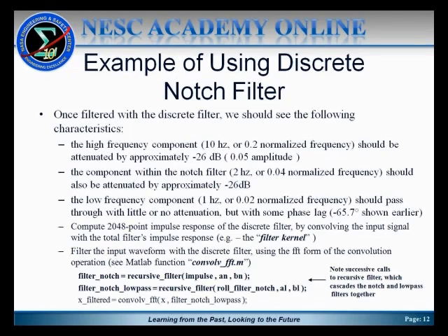And the two functions we're going to use, one we've talked about before, is recursive filter. That's just an implementation of a recursive filter where you pass it the thing you want it to filter, and then pass it the numerator and denominator polynomials of that filter, and then it will, in effect, implement that filter. Those are not built-in MATLAB functions. They're just MATLAB functions I've built for my own purposes. Then finally, there's a convolution that uses FFT, and that's what's shown at the bottom of the slide. The function name is convolve_FFT, and that just basically implements convolution but using FFTs.